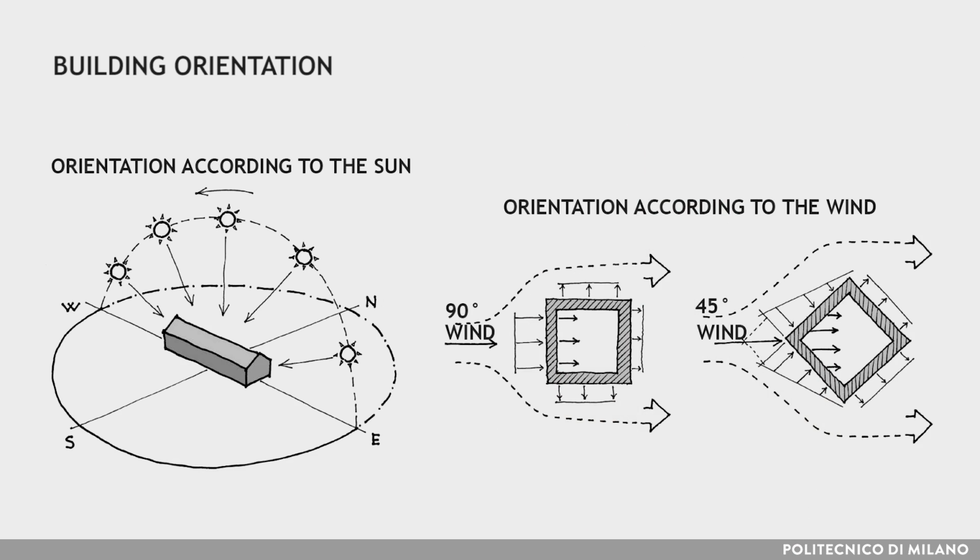Lastly, the building orientation should be designed according to the sun and wind in the area. Building orientation in tropical climates is very critical due to the interaction with the sun and the wind, from which the energy performance largely depends. Generally, within the East African community, the basic rules are: minimize facades facing east and west, and take into account local prevailing winds because of their connection with natural ventilation.